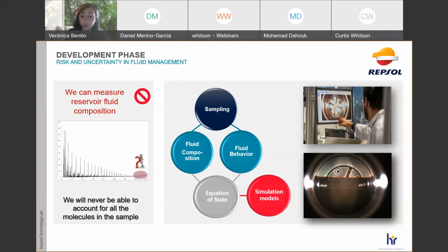An additional issue we have in those experiments is that they are not standard for all the fluid types. We have a big uncertainty present when we measure the samples, for example, especially in near critical fluids or heavy oil fluids. In those cases, the stabilization time of each stage of the PVT analysis plays an important role in the consistency analysis, because we could have different results of saturation pressure depending on the way we do the analysis.